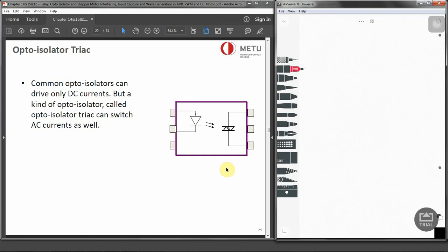So for any kind of stepping controlled motion, we can use stepper motors. And you might ask, what's the difference between a conventional motor and a stepper motor? Conventional motors have shafts which run freely, but with stepper motors, the shaft moves in fixed repeatable increments. So this allows us to move to a more precise position, which we are going to see in detail.